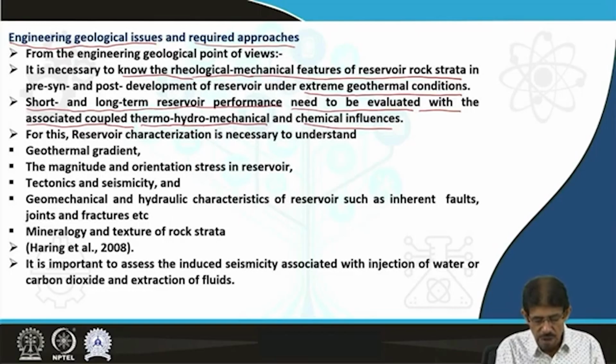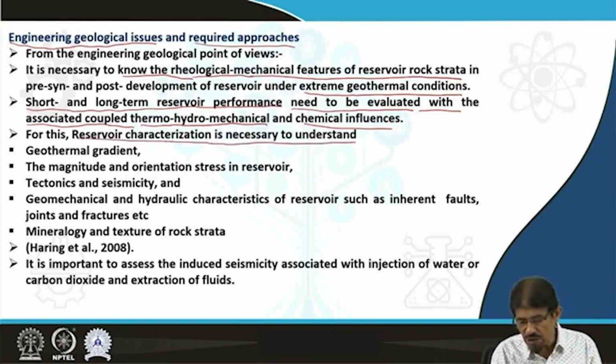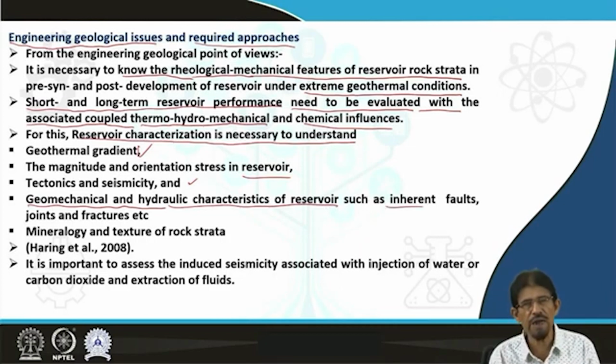For this, reservoir characterization is necessary to understand the geothermal gradient, the magnitude and orientation of stress in the reservoir, tectonics and seismicity, and geomechanical and hydraulic characteristics of the reservoir rock strata, such as inherent cracks and inherent discontinuities like joints, faults, fractures, and any type of discontinuity.